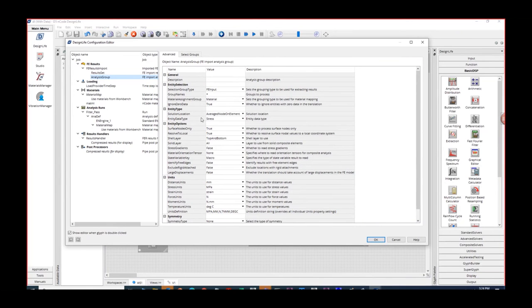If you want to do the real plastic strain based fatigue analysis, then we should not use any plasticity correction. Instead, under the analysis group, instead of using the stress, we have to use both the stress and strain.